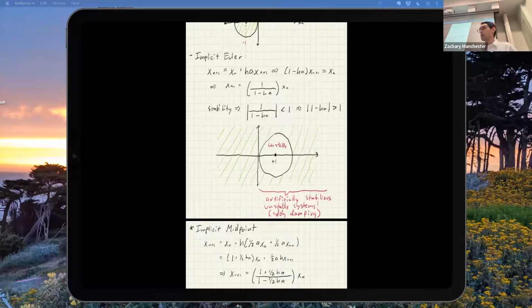So most of the robotic simulators use fixed step sizes. And they want to be able to run at relatively low sample rates. They don't have to run at crazy high sample rates. And they also want it to be just plug and play and just work, right? Without having to fiddle with all these things. This guy gets you pretty close to that because of this stability, right? Like it's basically almost never going to blow up. And I can make sure I'm never in here by just adding a ton of extra damping. So I basically artificially push things over here and live in that region all the time.